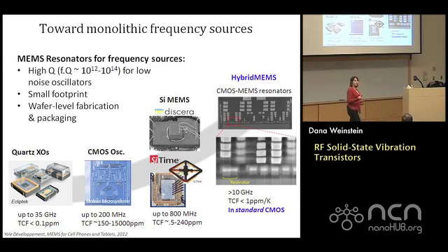So our goal in our group is to actually go a step beyond this and really implement completely seamlessly integrated resonators, acoustic resonators, into CMOS. We want to use the silicon because it's high quality factor, so we want front end of line processing of these acoustic resonators. But we don't want to have to deal with any of the packaging, any of the extra processing, any release steps or anything like that. We want to use the existing process and be able to scale to very high frequency and have our resonators side by side with transistors and connect to even at metal 1.